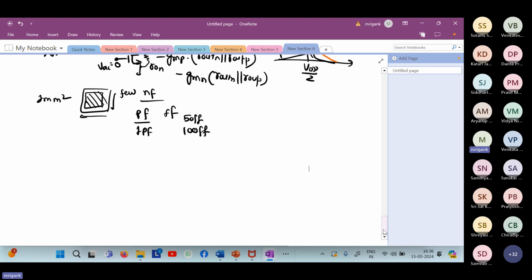Again, for VDSAT, there are a lot of device parameters. Your threshold voltage is another parameter, lambda is another parameter. The threshold voltage reduces as we go from higher nodes towards lower nodes; it keeps on reducing. If you are not reducing VDD, suppose you're using the same VDD for both of them, the current will effectively increase.